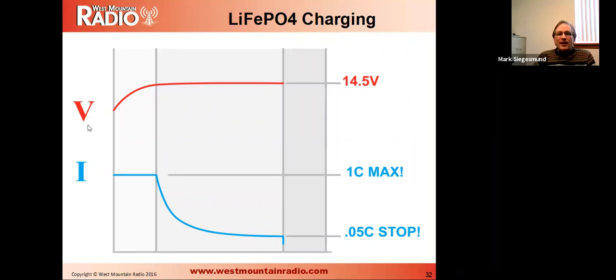The reason that I'm pointing out the fact that these two charging algorithms are different is, in general, you shouldn't be putting a lithium battery on a lead acid charger because it can damage it. Now, there are some lithium batteries that have electronics in them that will tolerate the lead acid charger, but you have to make sure you're using a battery like that if you're going to, for example, use your automobile to charge the battery.